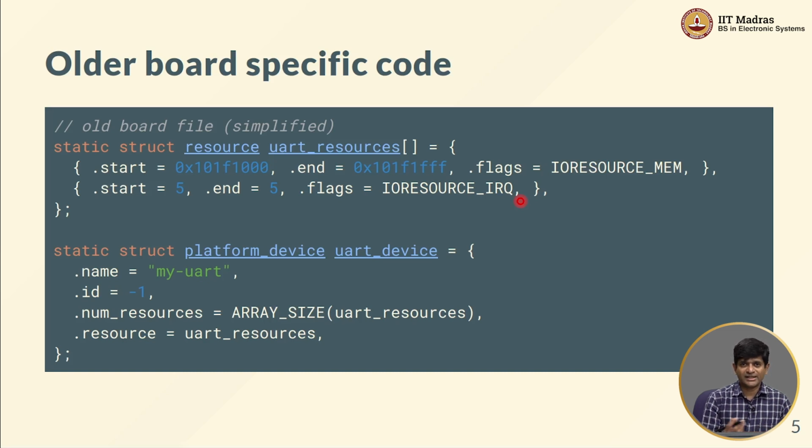Now, the way that interrupts work in practice is that I have something called an interrupt controller. I connect many different peripherals onto that interrupt controller, and that interrupt controller in turn finally goes and wakes up the CPU anytime that there is something new to be done, right. Which means that that interrupt controller also needs to be able to tell the CPU which device actually woke it up, right, or interrupted it. And that is done by specifying an interrupt number, right.